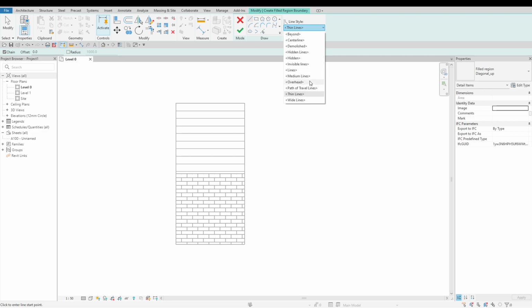Wide lines are significantly thicker and darker than standard line weights. They are typically used to emphasize elements in printed or on-screen drawings, such as cut edges in plan or section views, or critical boundaries like property lines and fire-rated walls. Thin lines are narrow and light, intended for less prominent features. They are ideal for detailing minor components, including fixtures, finishes, and furniture, ensuring these elements are represented without overwhelming the overall drawing composition.